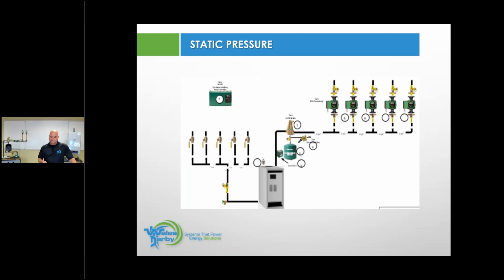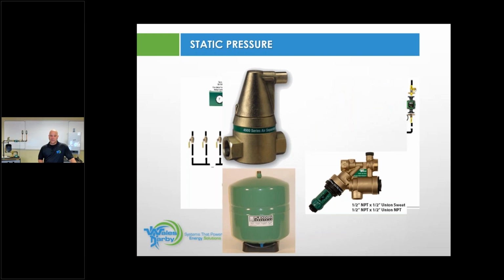And it's hard because the majority of everything you see out there, cast iron wise, is older equipment. They used to come packaged right here on the boiler, on the return, and then you would pump into the boiler, then you would pump into the expansion tank, then you would send it out to the system. It worked in most homes, but if you have a problem job, and we'll show you an example of it later, it's important to have that circulator in the right location and allow these items to do their job.